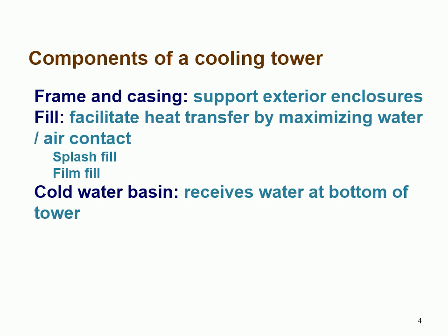Cold water basin. The cold water basin is located at or near the bottom of the tower, and it receives the cooled water that flows down through the tower and fill. The basin usually has a sump or low point for the cold water discharge connection. In many tower designs, the cold water basin is beneath the entire fill. In some forced draft counterflow design, however, the water at the bottom of the fill is channeled to a perimeter trough that functions as the cold water basin. Propeller fans are mounted beneath the fill to blow the air up through the tower. With this design, the tower is mounted on legs, providing easy access to the fans and their motors.